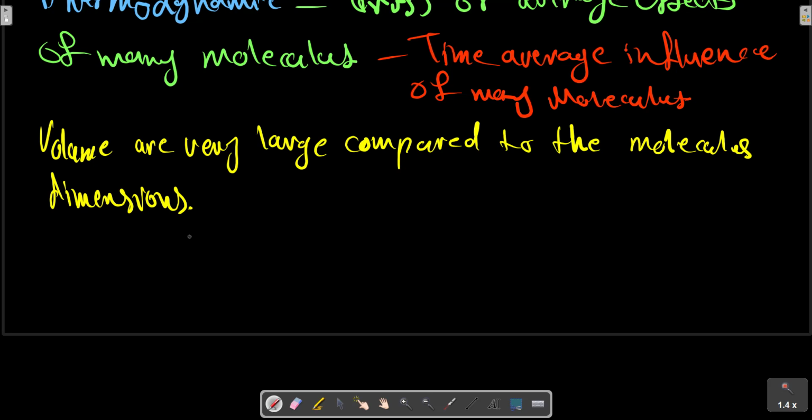The continuum concept is of course only a convenient assumption that loses validity when the mean free path of the molecules approaches the order of magnitude of the dimension of the vessel, as for example in high vacuum technology.